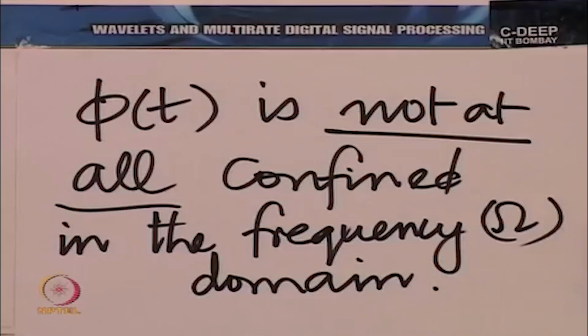Now, all this while in our discussion, when we talked about time and frequency together in the previous lecture, we had been worried about these side lobes, as we call them. We said, well, it is all right to look at the main lobe and talk about presence in the main lobe, but then we have these side lobes, and the side lobes are falling off only by the factor 1 by omega in magnitude. And as you can see, the side lobes have created a problem.